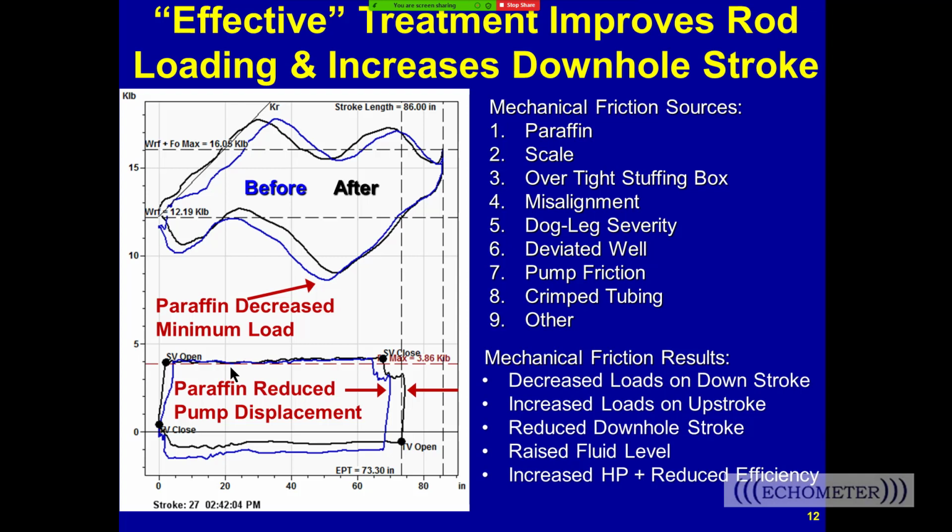There was a big discussion in industry about hot oil or hot water, and a lot of companies would take the hot oil from their tank, from the tank bottoms where the paraffin would collect. They would take the oil that's saturated with paraffin, heat it, and put it in a well, and that would cause the new well to have paraffin problems because the paraffin was saturated out of the tank.